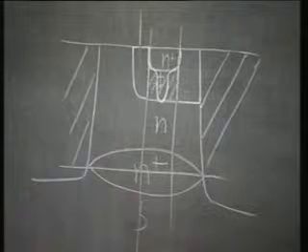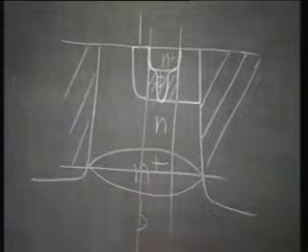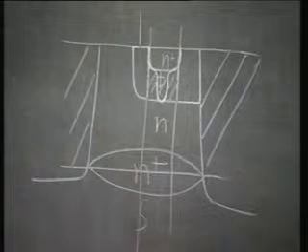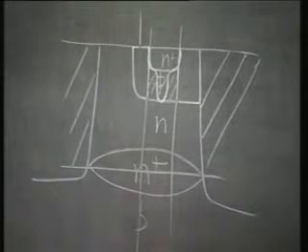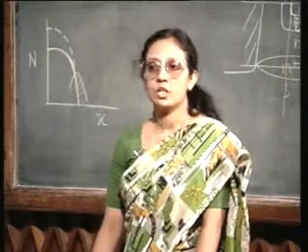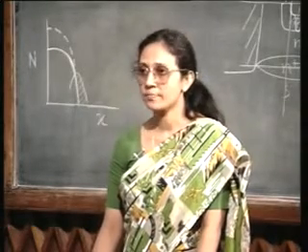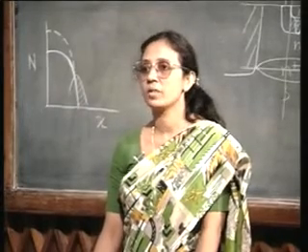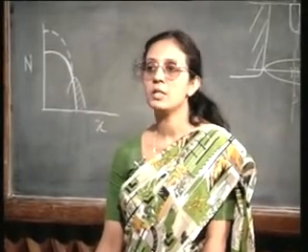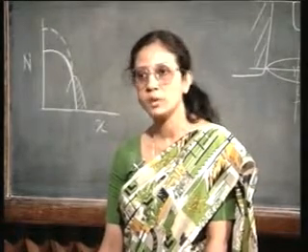You have an emitter collector pipe due to enhanced localized diffusion. You can have a base widening effect because of emitter push if you use phosphorus as emitter, and you can also have junction spiking, particularly when we are talking about a shallow base. Aluminum could spike the junction unless you have taken proper precaution by using an alloy which contains silicon along with aluminum.